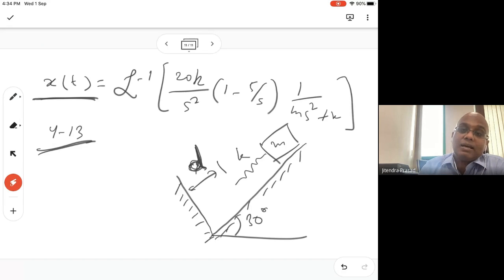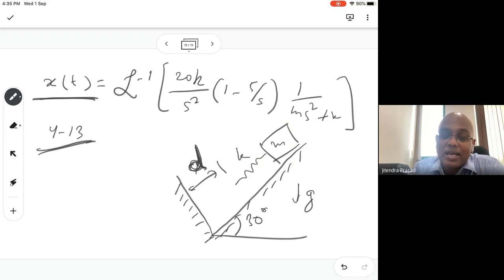So first thing is, we have to find out what is the velocity when it is making the contact. In such questions you can also use the energy methods, but here it is complicated, meaning that you will have the spring compression, then you have gravity. Because of that you have to take care of that, and you also have the velocity, so kinetic energy will be there, then potential energy, because of the gravity also. So it's complicated, but we can do it differently also.